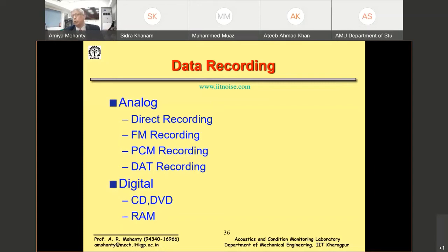I'll come to the story of conversion to the frequency domain a little later, but it is important in condition monitoring that if there are peaks in this spectrum at frequencies A, B, C, each of these frequencies relates to a physical parameter in that machine. So if a physical parameter A has gone wrong, the amplitude at frequency A is going to increase. So that is the power of vibration